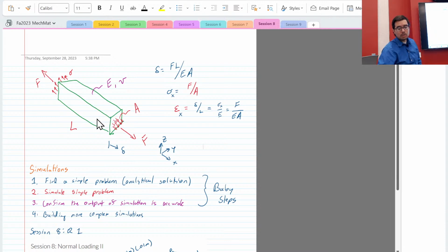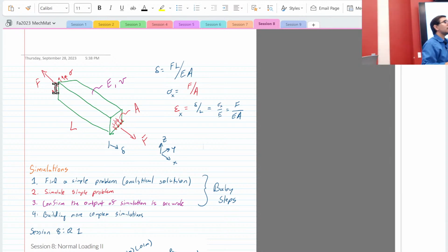Okay? So what you want to do is move over here, maybe right click, and do the query a little bit over in the middle region, and see if that does it. You want to take a snapshot, or use a query, where it's nice and continuous color. You'll see that there's often a gradient in color at the ends. So maybe try that. Other things.